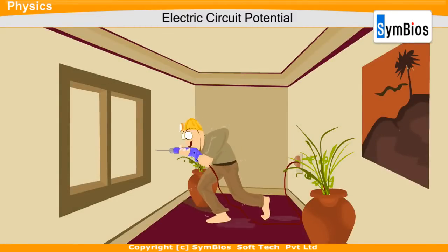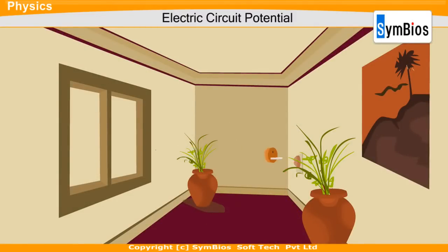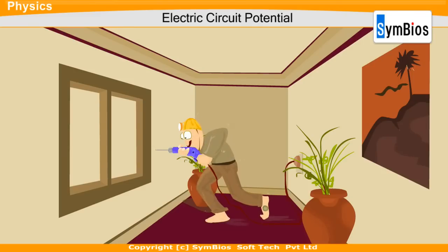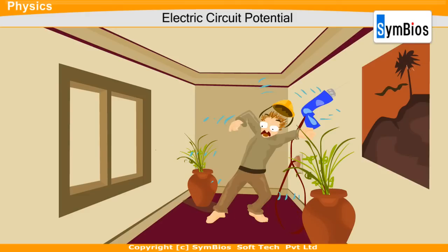Upon contact of a human body with the leaking switch, leakage power flows to the body, and if it is high enough to cause sufficient current to the skin, the body gets an electric shock. The minimum current a human can feel is thought to be about 1 milliampere.